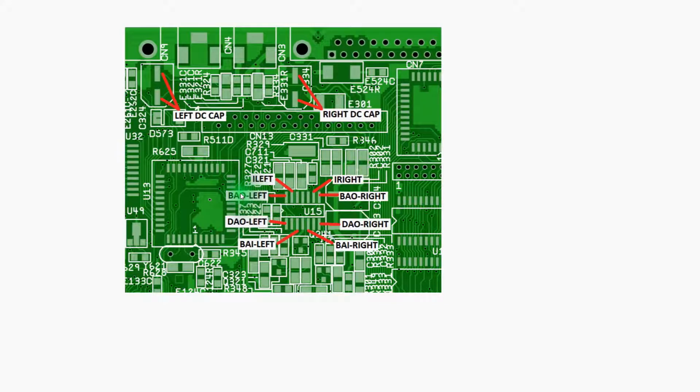That buffered audio out comes down here, the same signal. I've labeled it buffered audio in because it comes in on the left channel here. And I get that drive audio out for the left channel, and that drive audio out finds its way up to the left DC blocking capacitor into the output.